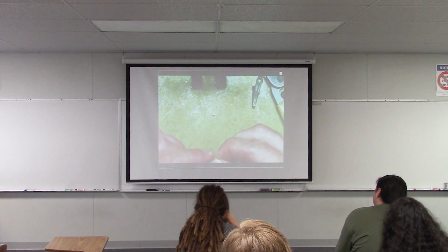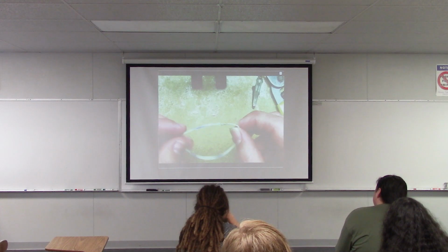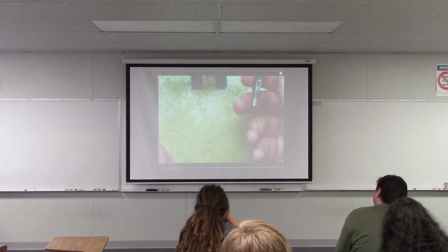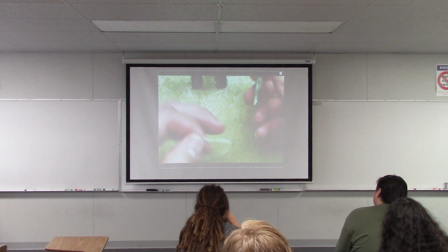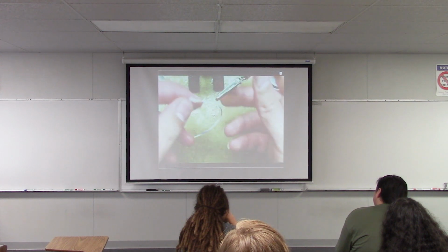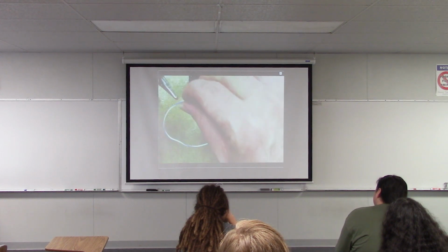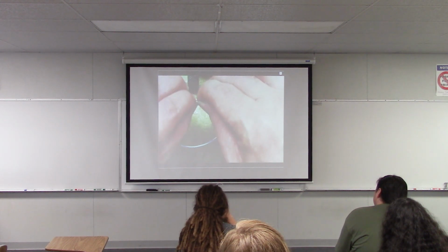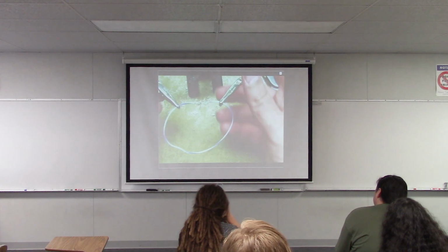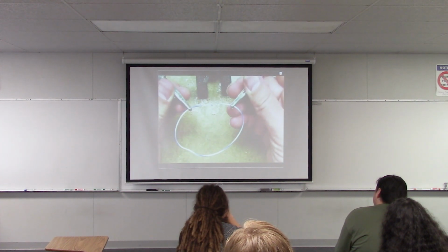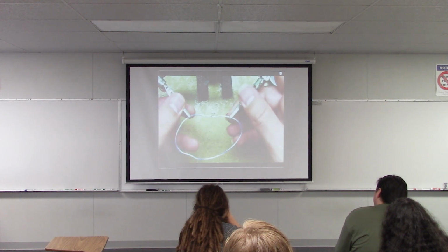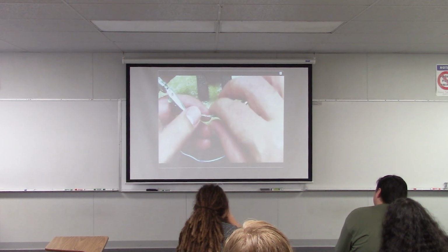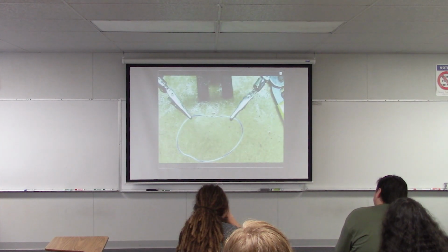And now the wire itself is kind of providing a mechanical connection. So we don't need to rely so strongly on the solder joints. Also, this will help keep the two ends of the wire connected to each other while we're doing the soldering. So it'll make that process easier as well. So once we have the wire stripped and connected to itself like this, we can actually start the soldering process.